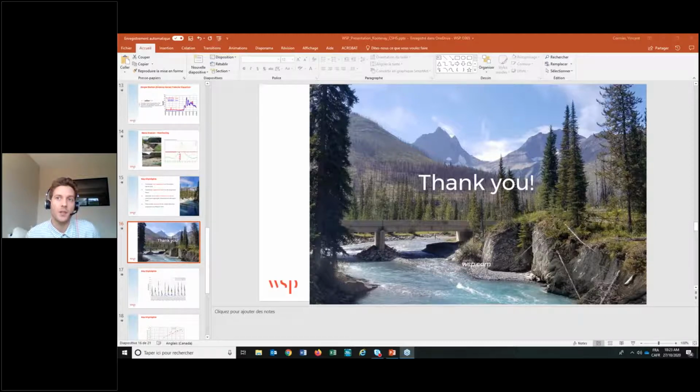We tried to have a flow measurement at higher flow to improve our confidence in the models. But we kind of tried to improve our confidence by having several sites on the same river, just to see if there's some repeatability in the unit discharge that were obtained, and there was. So the idea was to try to do something with the budget that was available to improve our understanding of the hydrology in the park, rather than just trying to rely on existing hydrometric stations.